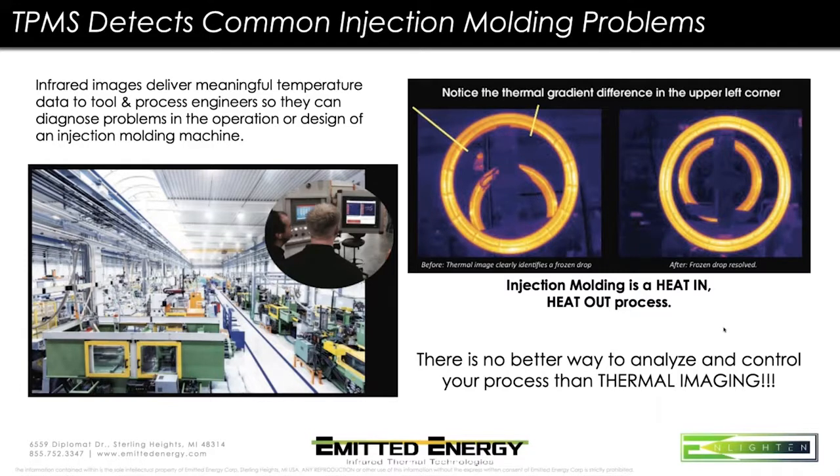It's a full part." I said, "Well, of course it's going to fill. You got 4 different parts filling in through here, but you've got one nozzle that's not the right temperature. It's coming around from the other ones." And I said, "Let's go take a look at it." Sure enough, it was clogged. And after that point, once we got them running, they never had a nozzle clog problem, which was their main problem. They didn't even realize it.